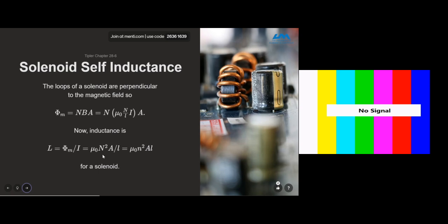And so you can imagine that this is something that we can either be frustrated by or make use of in terms of electrical engineering circuit design. If you want the current to change very slowly, you would need to have an inductor with very high inductance, and if you wanted it to be very quick, you would want to make sure to minimize the inductance in your circuit.